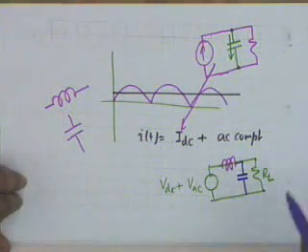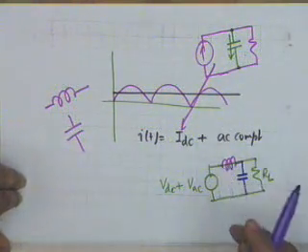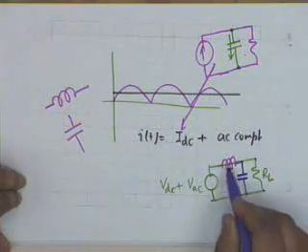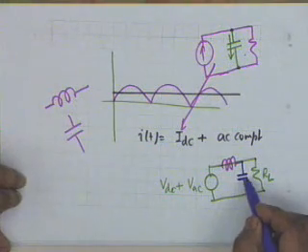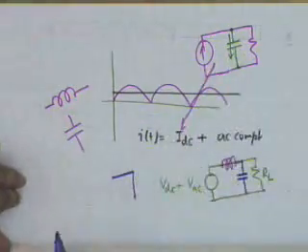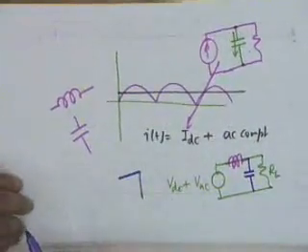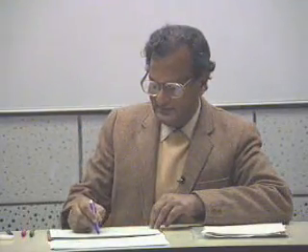All right. Accordingly, this is called a capacitor filter. If you have a single inductor, it's called an inductor filter. If you have a situation like this, an inductor and a capacitor, it is called an L filter. It looks like the letter L looked from your side, okay. This is called an L filter. Or you could have an inductor, then a capacitor, and again an inductor, then the load. This obviously looks like the English letter T, and therefore this is called a T filter.